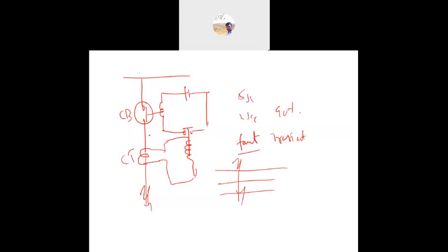Most of the faults on EHV and UHV transmission lines are caused by lightning, flashover, and overvoltage due to insulation failure. These are short-time faults, so we can call them transient faults.